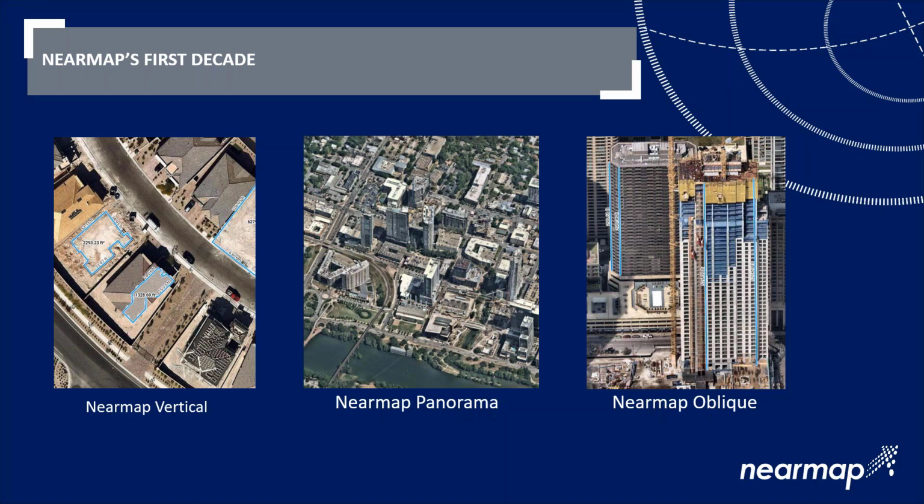The 3D content that we produce comes in at a 15-centimeter resolution. The accuracy statements across all types of our content are 28 centimeters horizontally and 40 centimeters vertically.